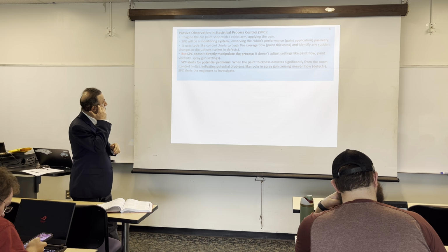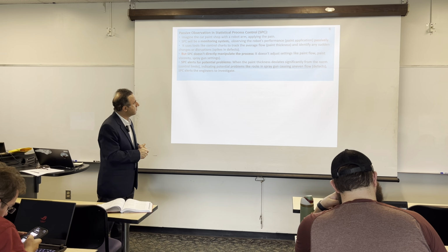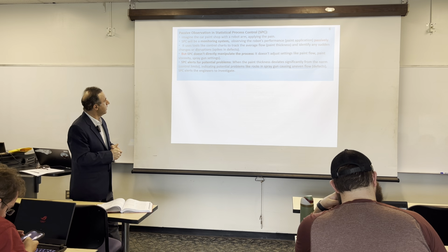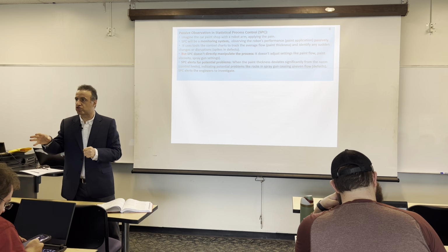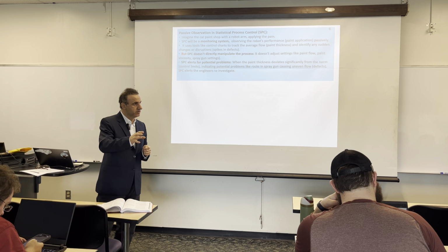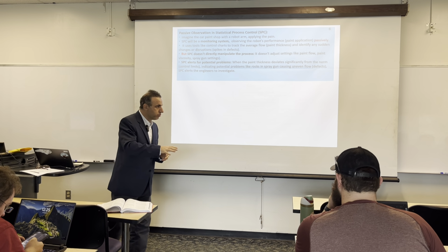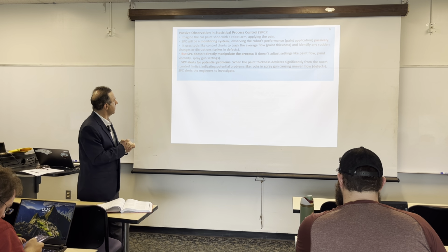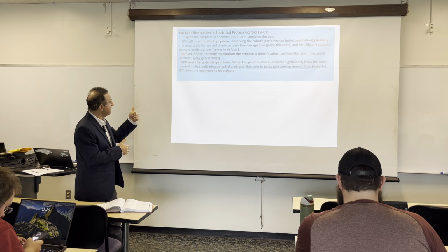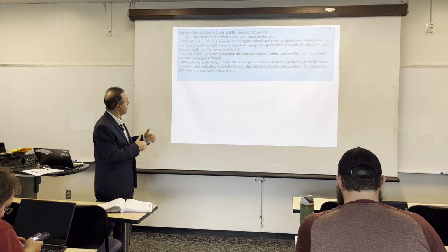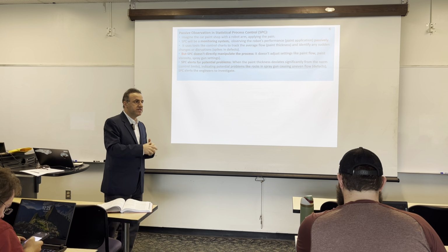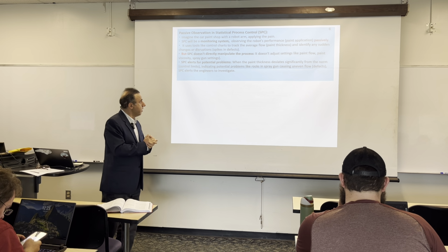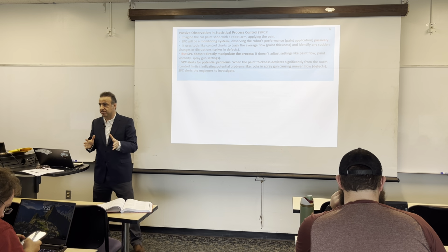Then we use SPC to monitor the system, whether the robot performance is correct or not, right? Then we use those X bar chart, R chart, S chart to analyze whether the performance is in control or out of control. Okay? So SPC does not manipulate the process. It will give you an alert.